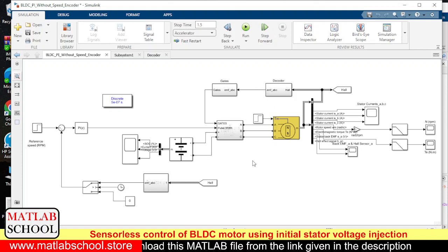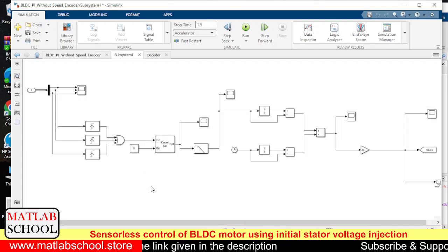Here we have used a peculiar technique to control the speed. These data are coming from the Hall sensors. Initially the Hall sensor data will be in the form of pulses. Later it will be in the shape of square wave. Then it will be converted to pulses by using these three edge detectors. It will be detecting the rising edge, and we are muxing it. We are putting it through the AND gate, OR gate. So we'll be getting three continuous pulses.